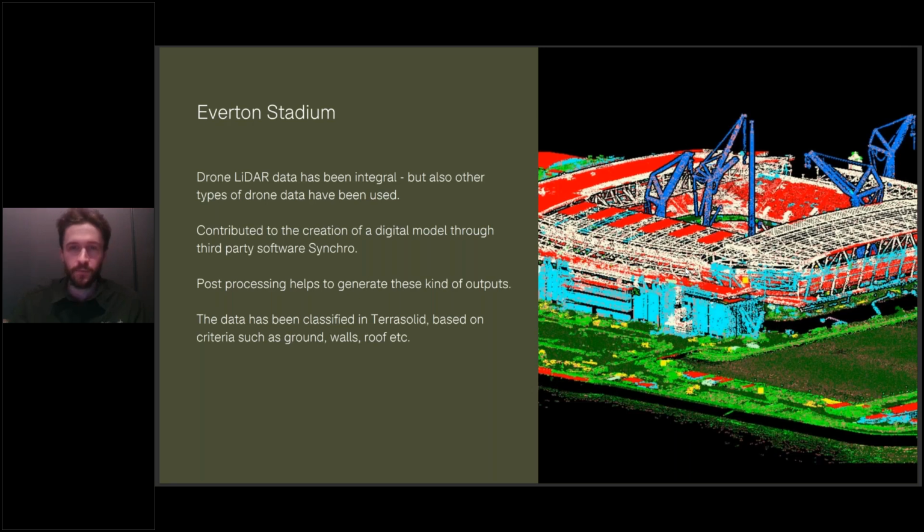So that brings us on to the next case study, which is work with Murphy Geospatial at the HS2 site. Murphy have been using the L2 for measuring the ground surface. This has been quite key with the L2, with it being able to penetrate further through vegetation with its 5 returns.